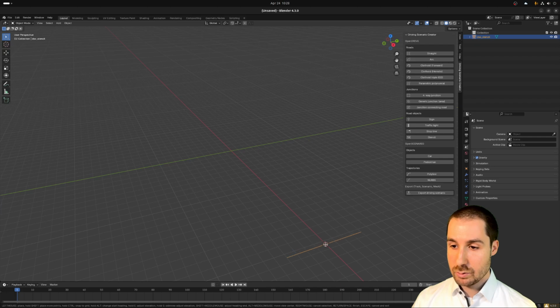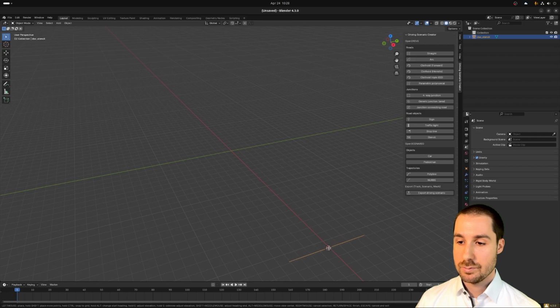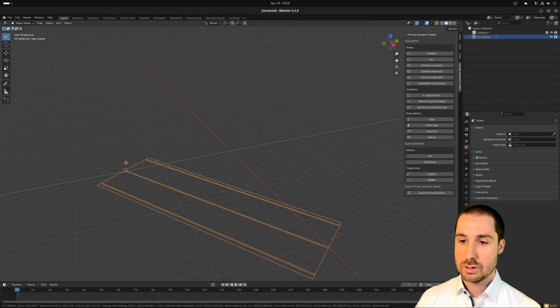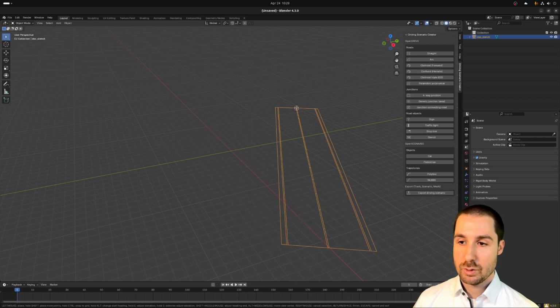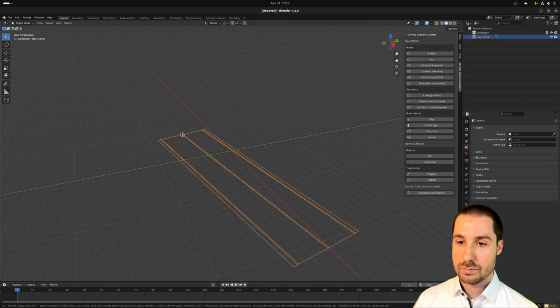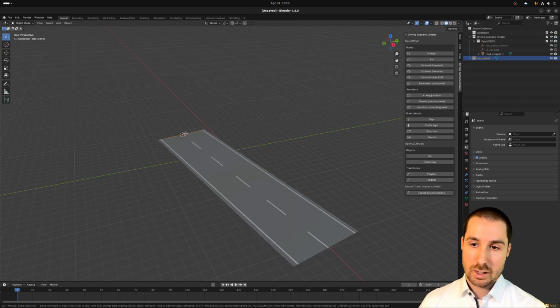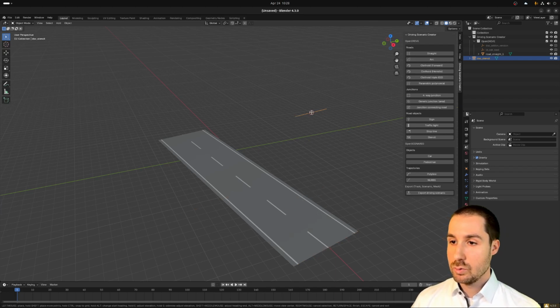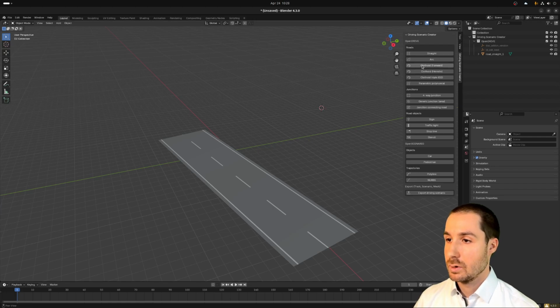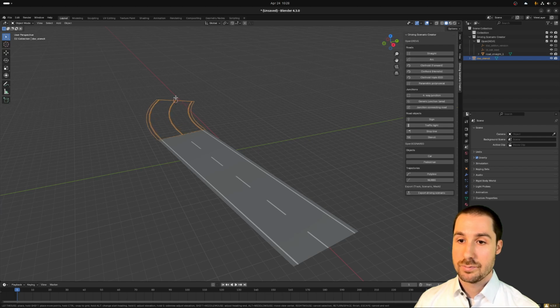And what you can do now is select where your road should start. And you can just drag it here and put it in a certain orientation that you want. Let's put it like that. And simple as that, we have our road section with 2 driving lanes and a border. You can also use other road types here. Let's put an arc to it, like that.